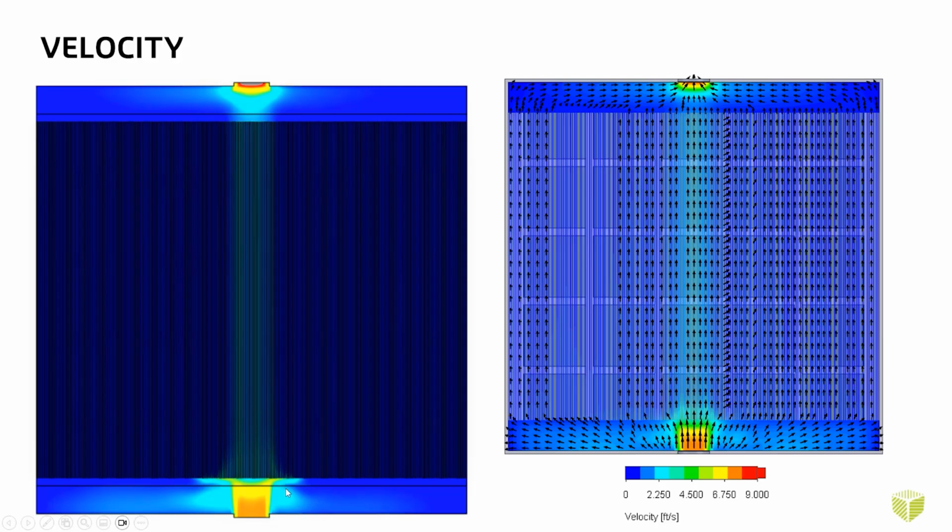But I do want to point out this sort of very subtle deviation there along that solid black horizontal line. That's where my mesh changed in size, where it went from the large cell to the small cell. So that's more proof of when your gradients between your cells are not good enough. Like your growth ratio should be improved when you start to see these deviations. That's not good.